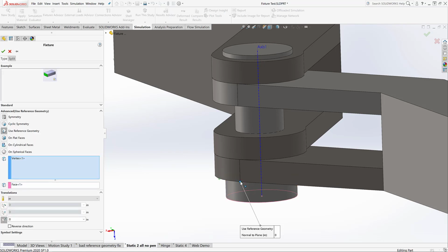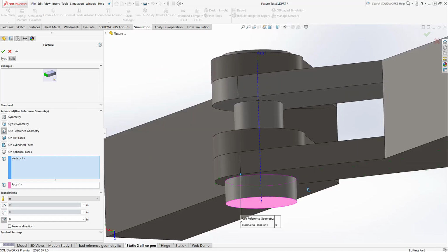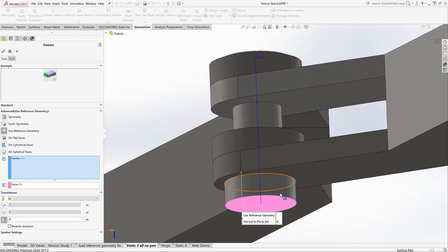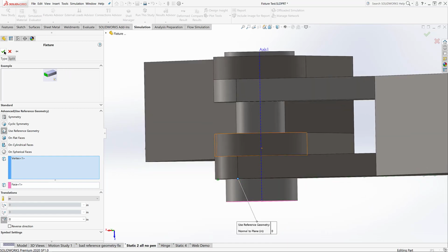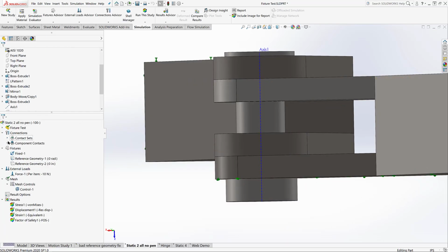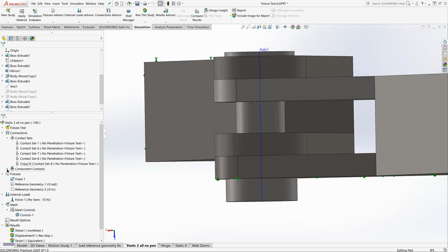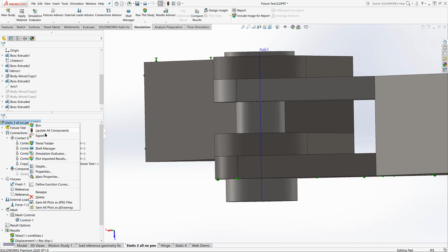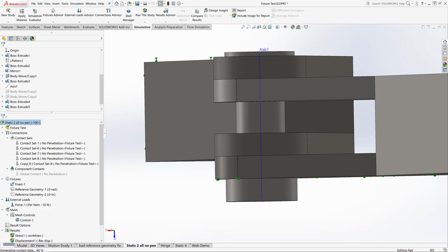Yeah, so here we can also specify a vertex with this face. So we're essentially saying this one can't pass much farther. Going to basically say 0 translation. Another way of fixing it in place. Great. I'll just run this guy, take care of the last question.